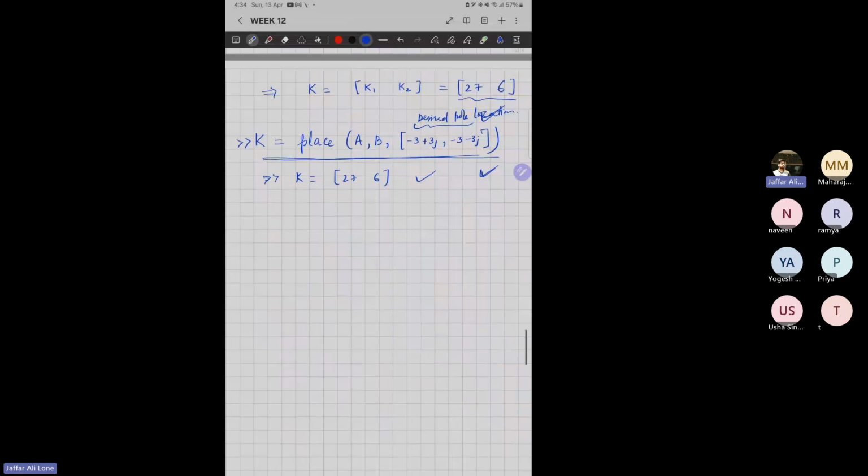Now you will solve it, and solve it quickly because we have to do some other questions as well. So your A matrix is 0, 1, -1, 0. Your B matrix is 0 and 1. Find K equal to K1, K2. Sometimes you are asked this K1 or K2, so in that case you'll eventually have to solve it. Find K such that my closed loop poles are placed at -1 and -2. Yeah, quickly.